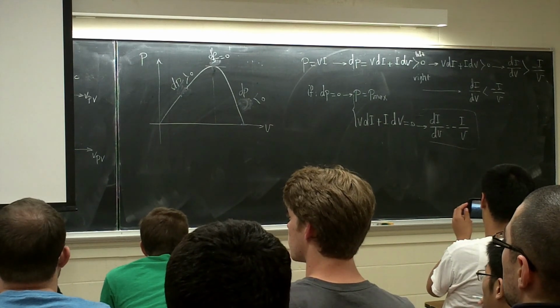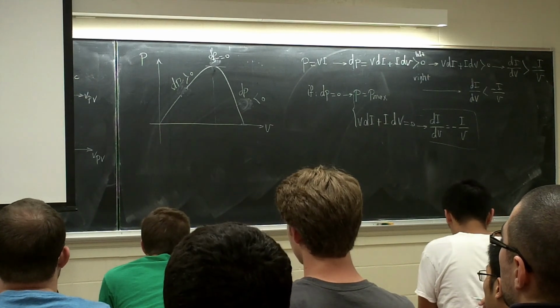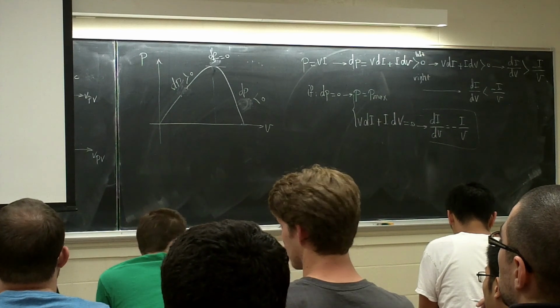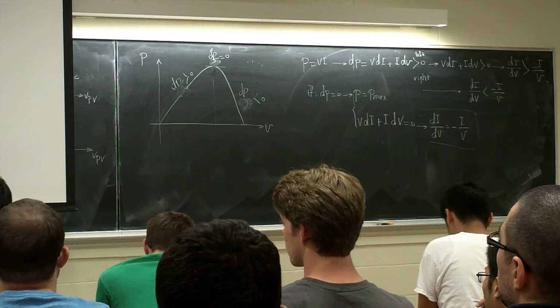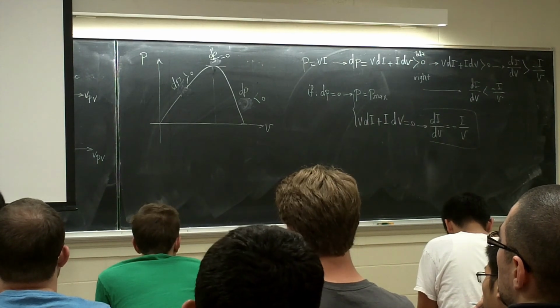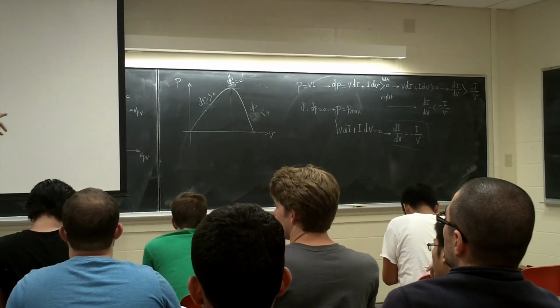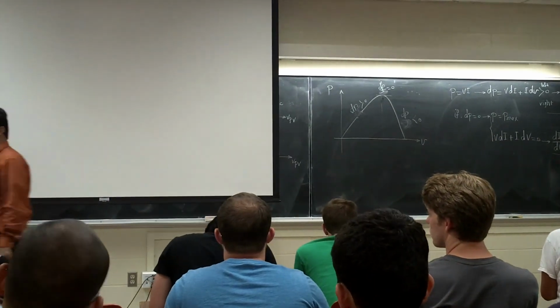Or if you don't want that, just use a fixed voltage again. You can say, I'm going to select 2 volts, it's not that big of a deal to go either this way or this way. I'm fine with that. They call it incremental conductance, and you can see why conductance: it's based on I over V. V over I is the impedance, I over V is the conductance.